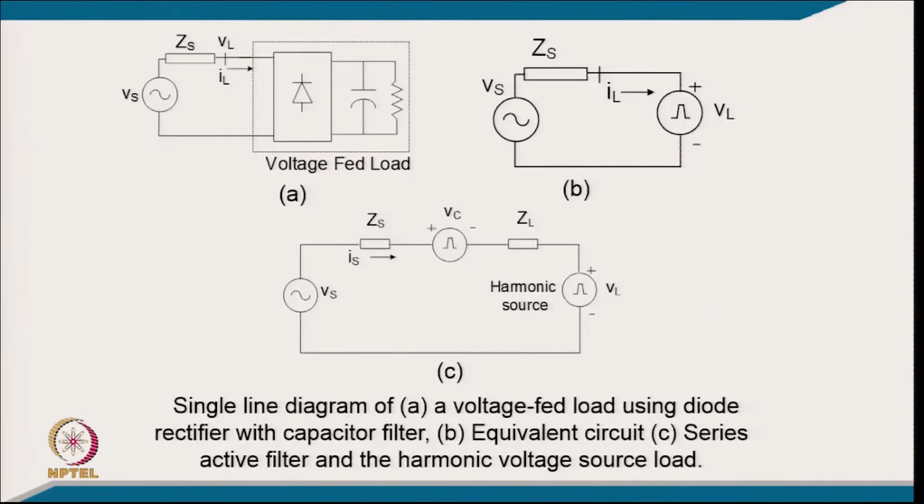And this is the typical case you can think about, which I was mentioning, that you have a voltage fed kind of load, and you draw what you can call uncontrolled current. You can think about how it really behaves, and you can typically inject a voltage in a way that you can reduce the harmonic current also.